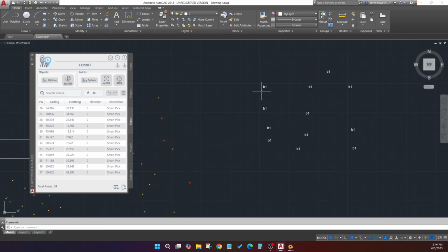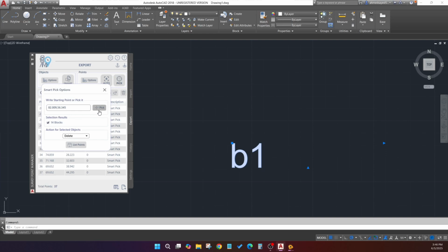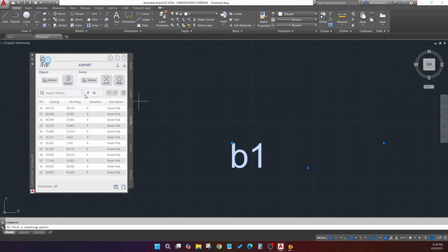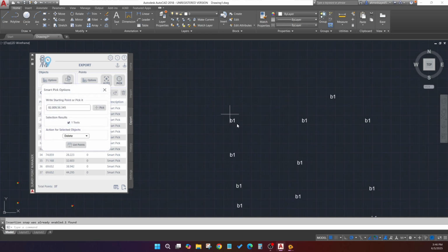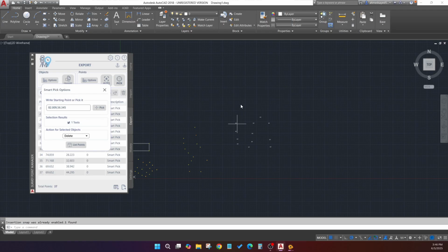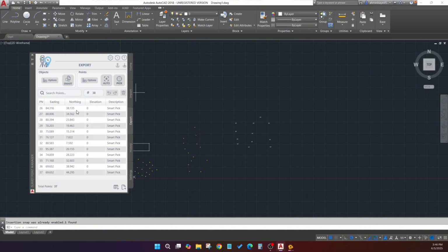We'll move on to texts. This scenario may occur with some devices that export text only, or only texts are available. Click Pick Start Point again and pay attention here. You mustn't use a previous start point because it will number points from the previous position. This will cause a big issue where all texts are numbered based on another start point.